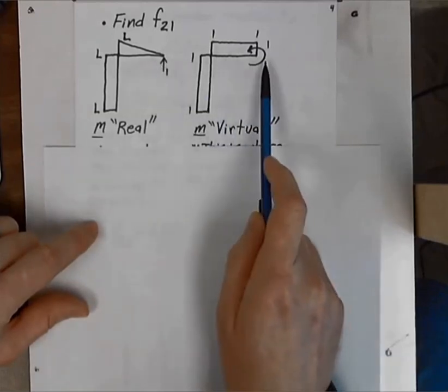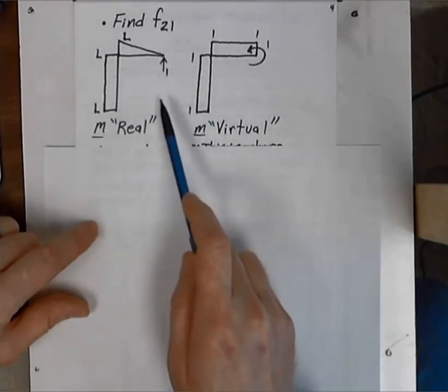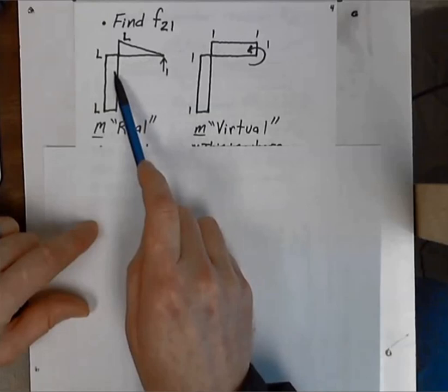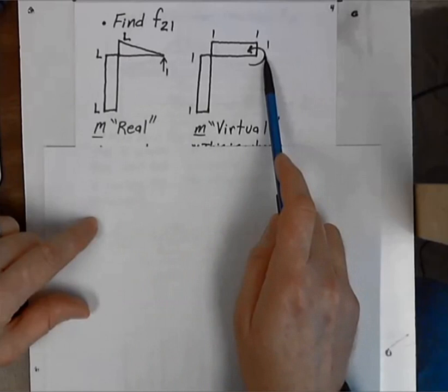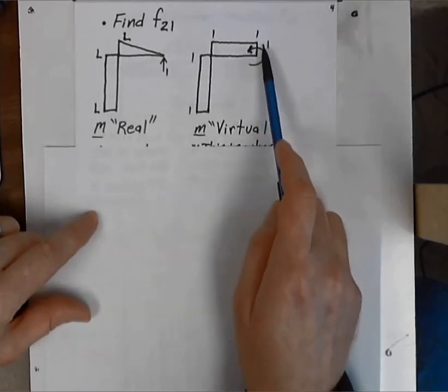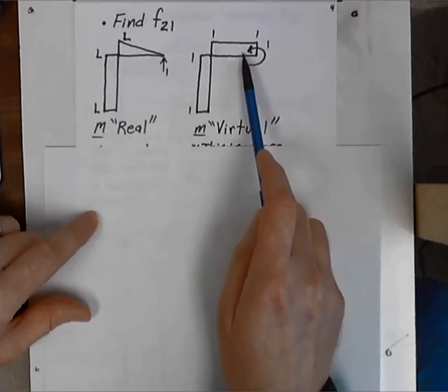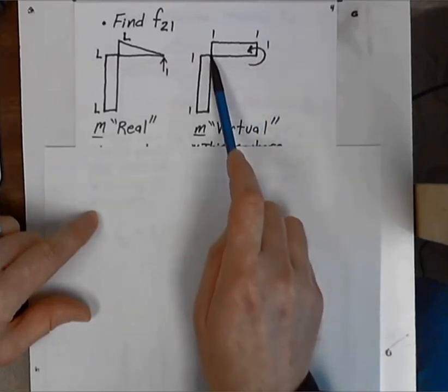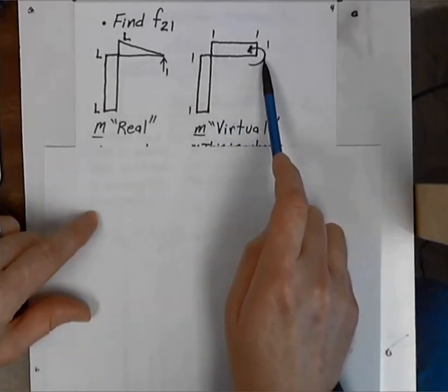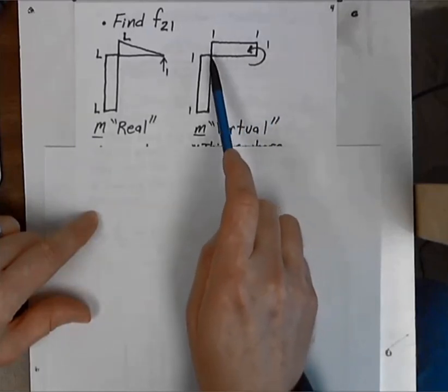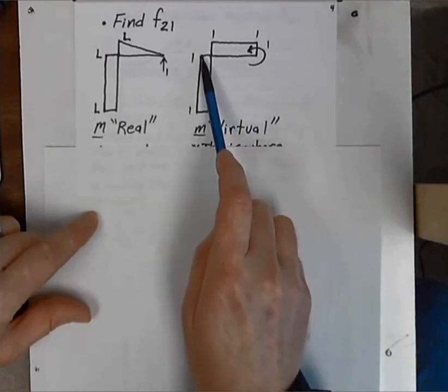So we have to consider these two loadings on our structure and construct the moment diagrams for each case. We already had this situation when we did F11, and so we know it looks like this. Then if we look at this one here, we have an applied moment of magnitude 1. It causes a moment of 1 at the end. Over here, if we had some moments about this point, and we found the internal moment here, we would find that it must be equal and opposite to that, and so we just have a constant moment of 1 in here. Again, due to joint equilibrium,